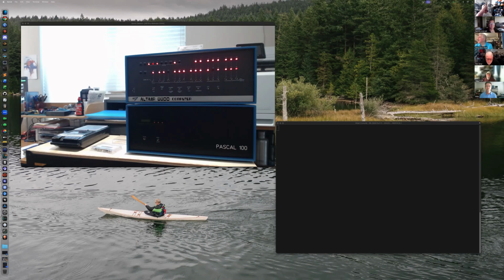Awesome. We've also been talking. The UART I happen to have doesn't need minus 12. Right. Yeah, there's flavors that work, but some of them require multiple supplies. So the new version of the board has a little 3-way jumper for turning the minus 12 on and off, on the off chance that one of those that doesn't need it doesn't like it either. In general, most of them don't care about that pin, but it's better to have a jumper just to be safe. It opens up that many more chips that could do it. It's worth the 17 cents.